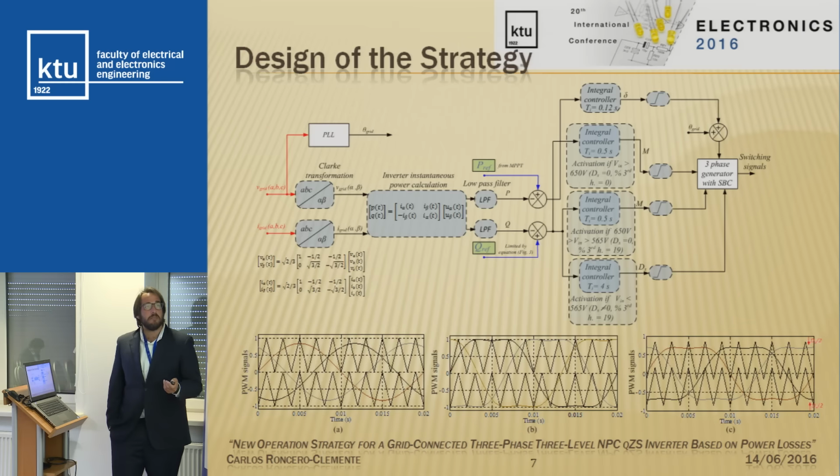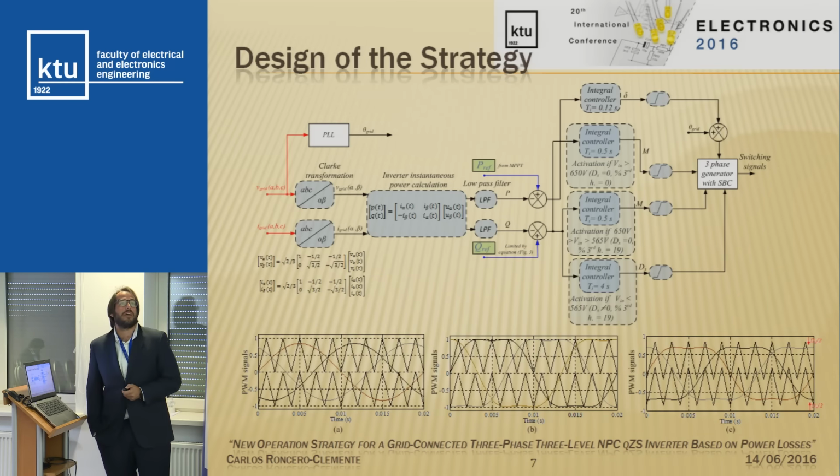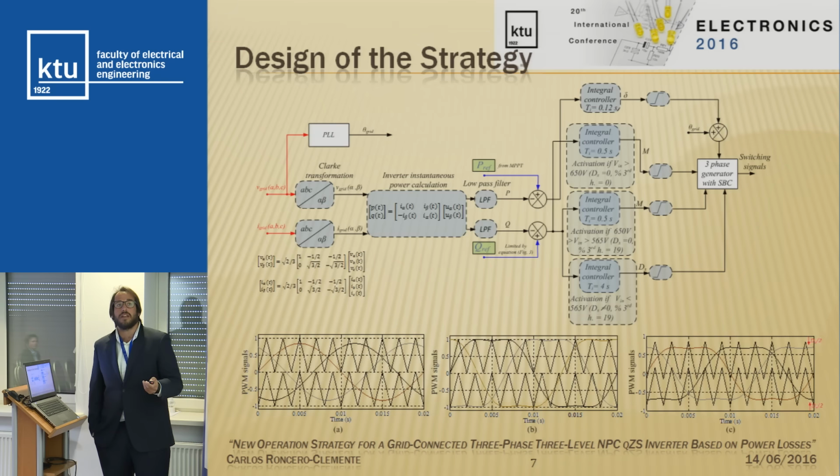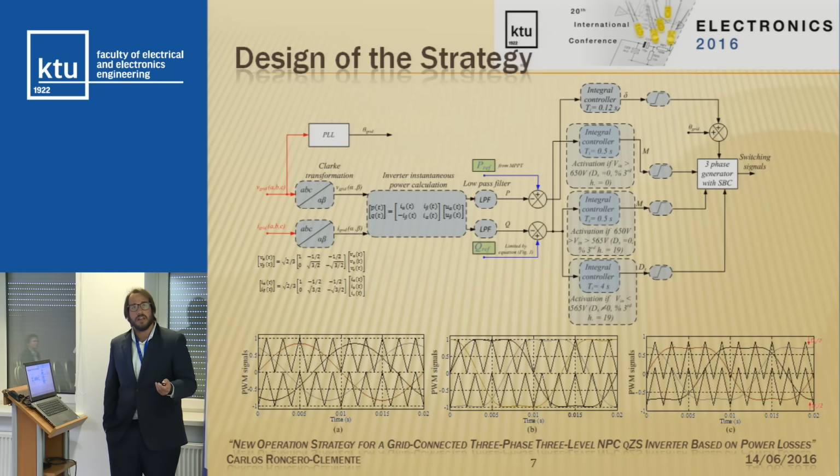Here we can see the implementation scheme of our power converter. We can see how with the delta angle we regulate the reference power with a simple integral controller, and the reference reactive power can be tracked by different approaches depending on the input voltage range that we find.